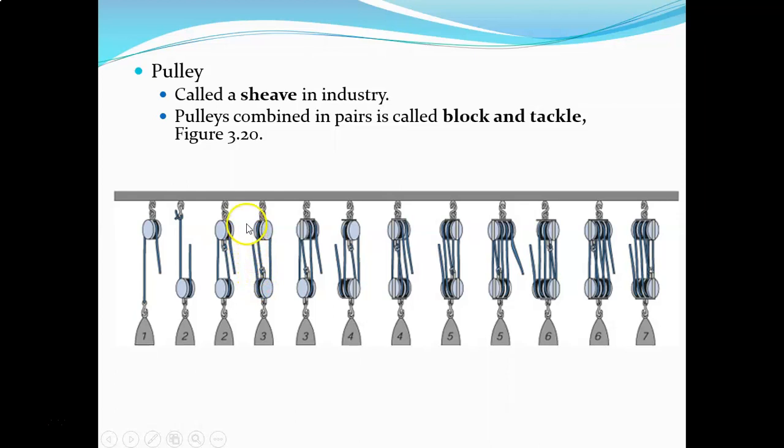So you can look at example 4, which is a mechanical advantage of 3. You're pulling up. So you do count that rope as your supporting load because you're pulling up against gravity. So you've got 1, 2, 3 ropes in that scenario. Okay, I'm going to stop with the pulling upward examples because everything we're going to talk about going forward is going to be in a more practical application where you're pulling down on the rope.